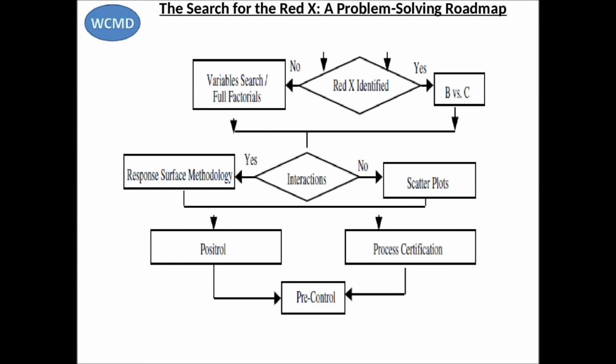One of the weaknesses of industry is that engineers and technicians attempt to control a process by checking the product it produces. That is too late. The clue generation technique of product process search is a DOE technique that can separate important process variables from unimportant ones. Variable search and full factorial take DOE further to distill the important variables and their interaction effects. Scatter plots and response surface methodology establish realistic specifications and realistic tolerances for each important variable.